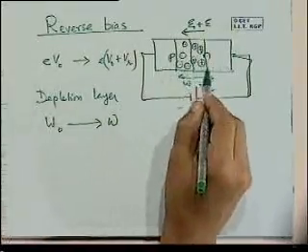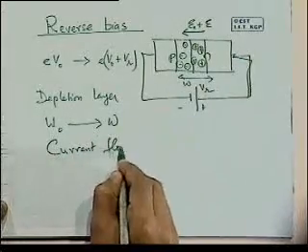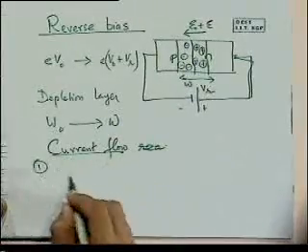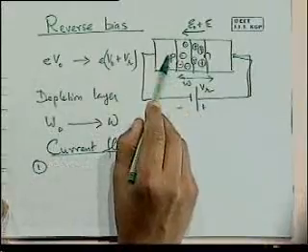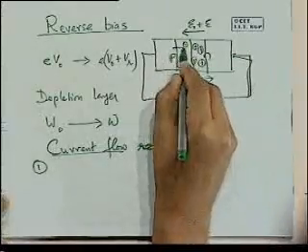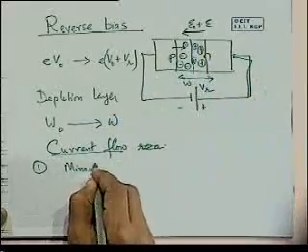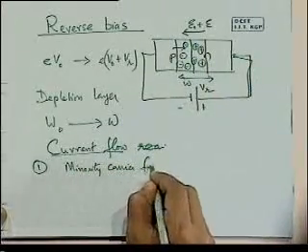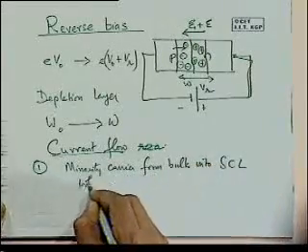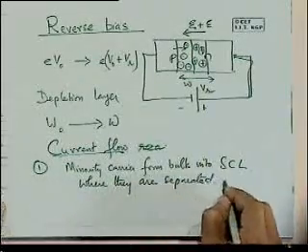The current flow that we have under such circumstances is for two reasons. One is very much like the Shockley model we have, namely that minority carriers can now go from the P side all the way into the space charge layer here, where this built-in field will separate them. So again here we have minority carriers from the bulk into the space charge layer, where they are separated by the field, or they drift under the field.